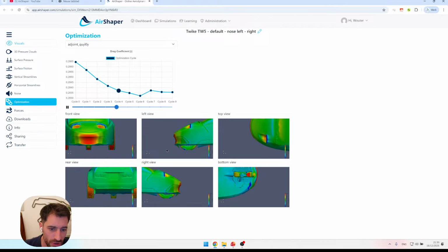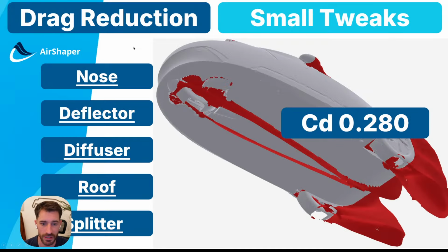Because pushing more air underneath the car, left and right, actually feeds more high momentum, high energy air left and right of that very difficult open front wheel area to then actually feed that energy into the wake to reduce the wake that we saw behind the potato, behind the front wheel. So this will be highlighted further down the presentation as one of the key features of the optimized design.